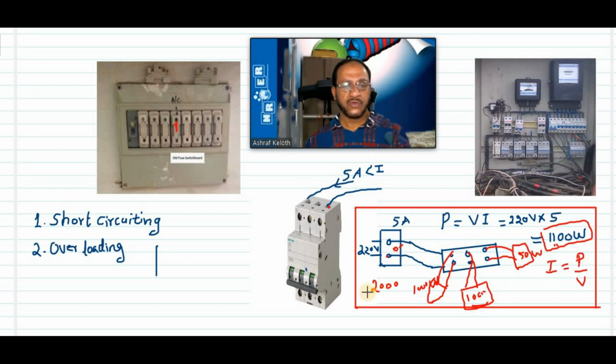the flooring, and you want to use this 2000 watts machine. Where can you connect that machine? At which point will you connect it? Can you connect in any of these lines, this area, here or here, anywhere? These are all branches. All these branches are 5 ampere. You cannot connect anywhere. You have to go to the main switchboard here.